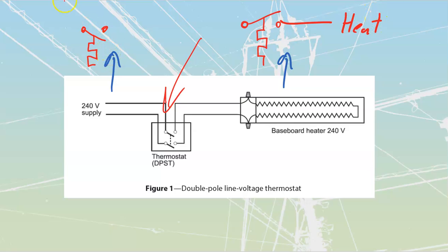And then if it would start to cool, the temperature would fall and then our heat would go and turn on. This one over here we would use for a cooling type of system, because we would see that as the temperature rises, it's eventually going to go and kick this switch. It's going to hit that switch. When it hits that switch, it closes and activates our cooling type of system that we will have. Either one of these is going to be our standard symbol.